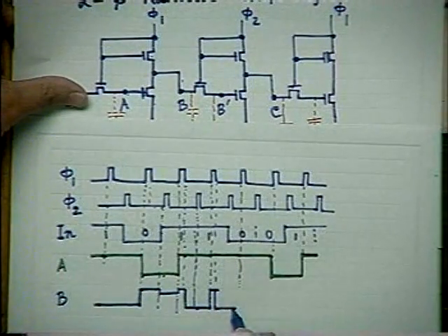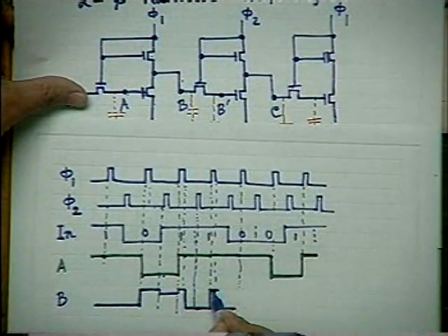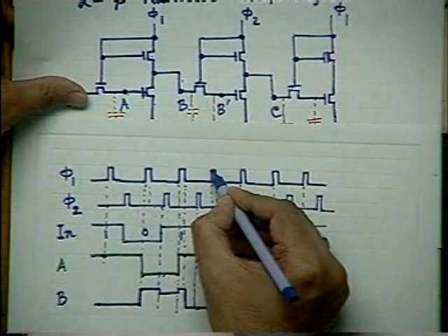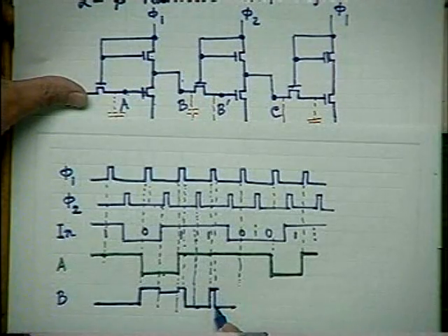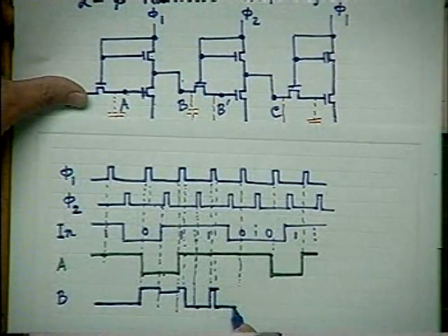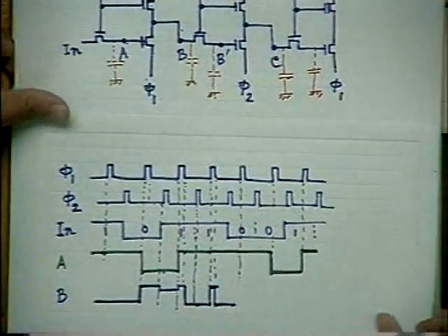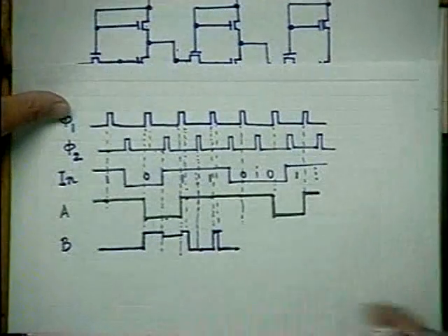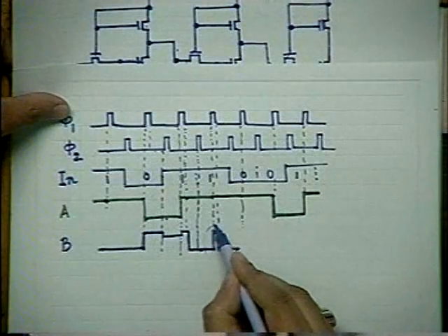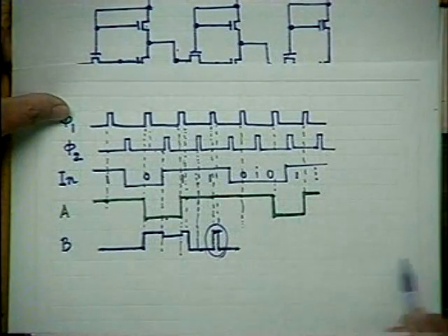Again, for a short time, this is high, and it goes up while A is high. So again it falls. After the short clock duration of the phi 1 pulse, it is on only for that time. But then again it goes to 0, because A is kept still high, so this transistor is on. Please remember this. And that's how, do you know what this is called? It's called a glitch.